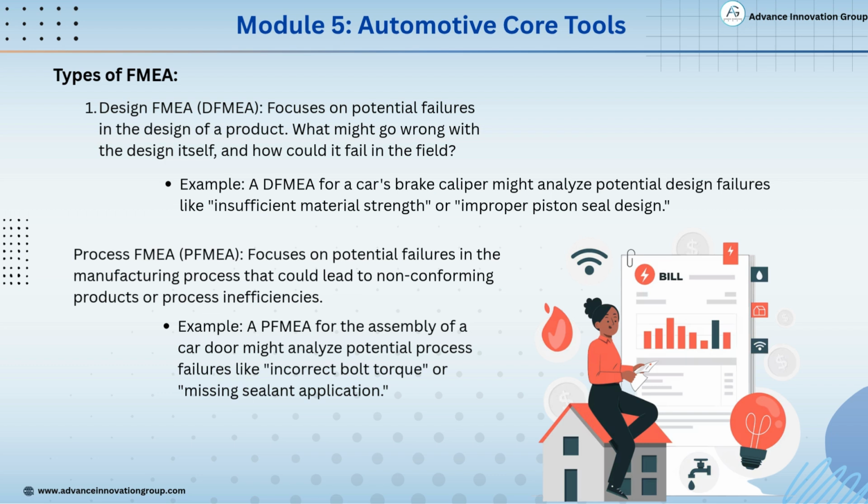It helps us think about what might go wrong with the design before the product reaches the customer. For example, a DFMEA for a car's brake caliper might point out issues like insufficient material strength or improper piston seal design. These are failures that can affect performance and safety.